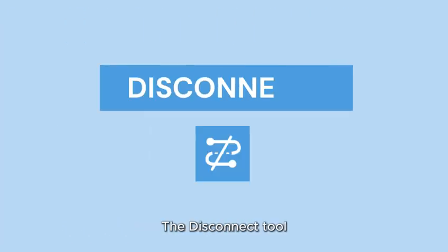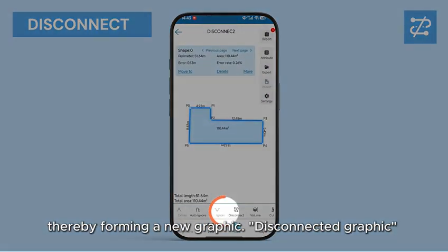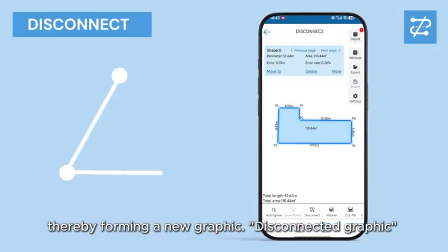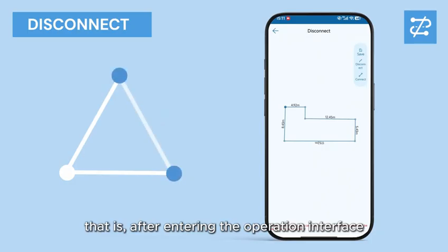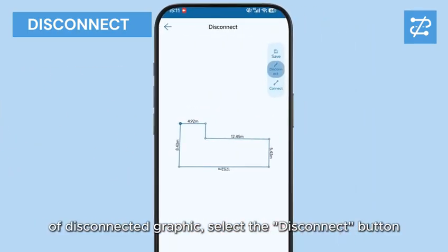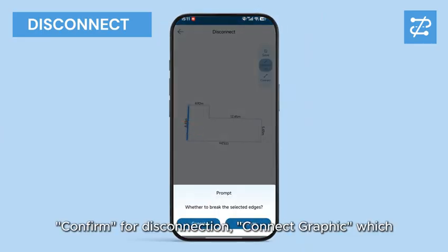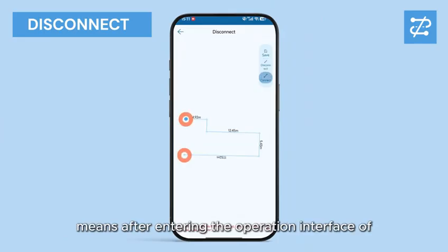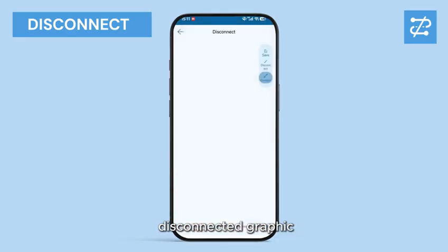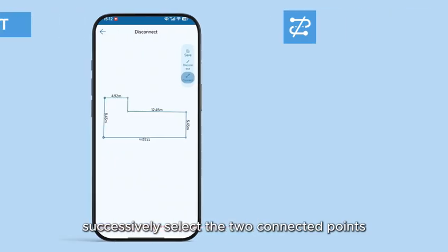The Disconnect tool can disconnect or reconnect graphic line segments, thereby forming a new graphic. To disconnect a graphic, after entering the operation interface of disconnected graphic, select the Disconnect button, then select the corresponding line segment. Confirm the disconnection. To connect a graphic, after entering the operation interface of disconnected graphic, select the Connect button, then successively select the two points to be connected.